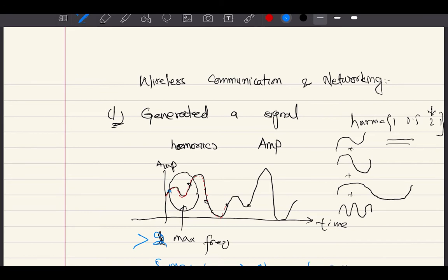The Nyquist criteria is related to the sampling of the signal. It is required to sample the signal properly so that there is no aliasing problem, and the signal is recovered the correct way when it is received. So you have to sample the signal at proper points, and that is the kind of sampling we did previously, which we saw in the sampling lab.